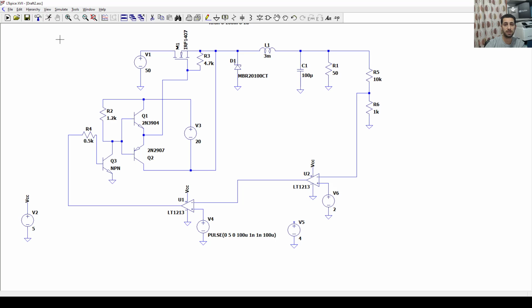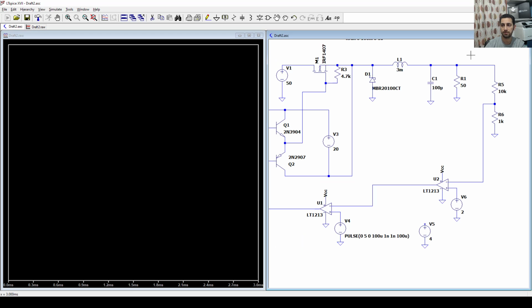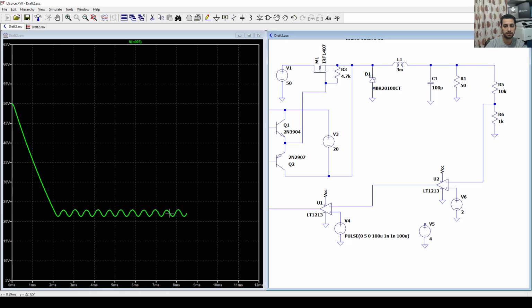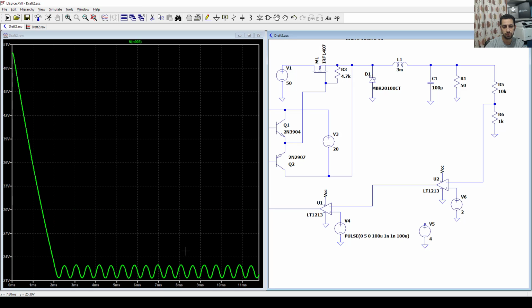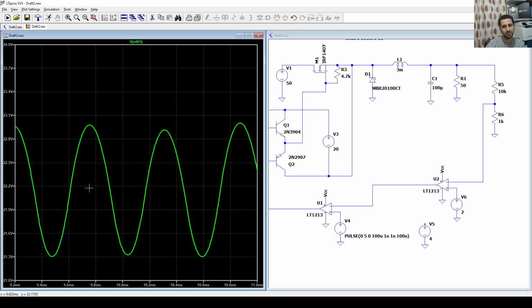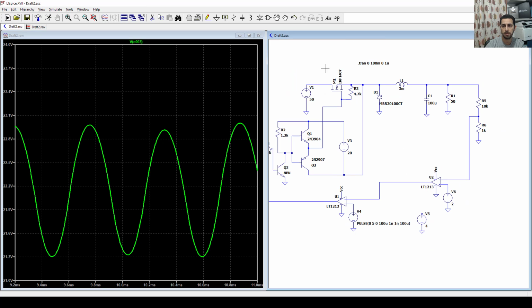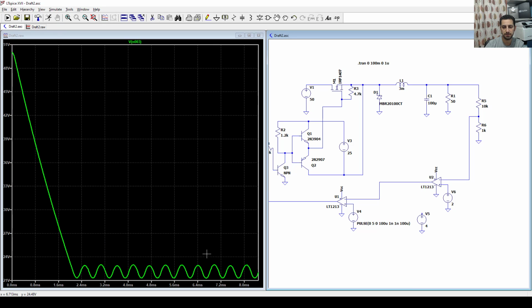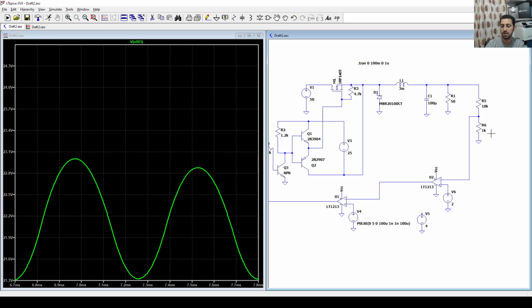Okay, so now let's try to run it again, because we learn from mistakes. What is the maximum value? Yeah, it seems very close to 20. Okay, so let's now stop it. Very close to 20. It's 22, okay? There are some voltage drops maybe across my transistor, because I'm driving it this way. Maybe I can drive it harder by supplying higher voltage here, for example 25 volt. Yeah, it might enhance it, but not that much, I believe. We'll see if there are some better results. No, it doesn't seem that. Still 22, okay? So now what is next?